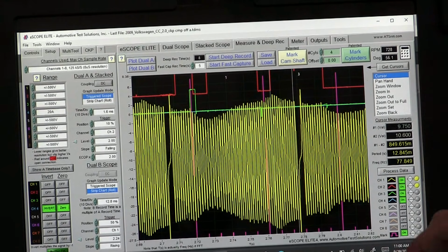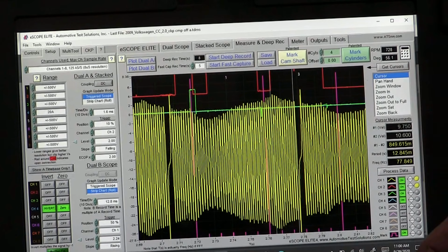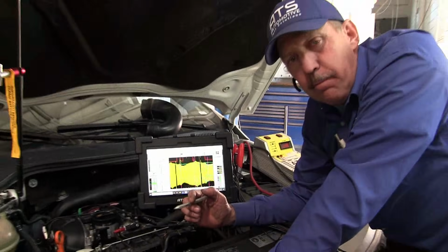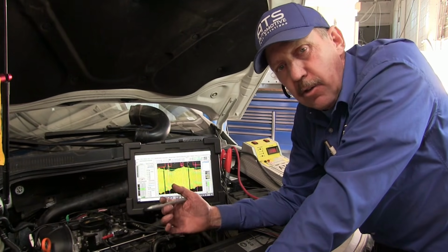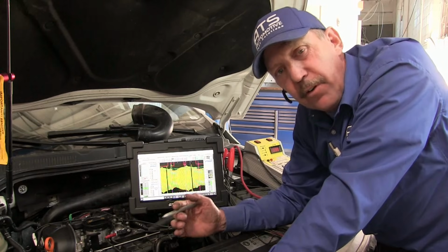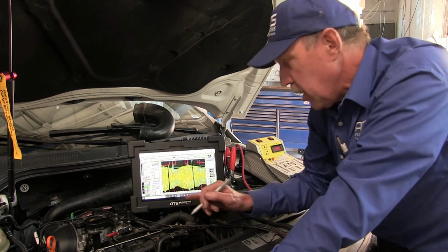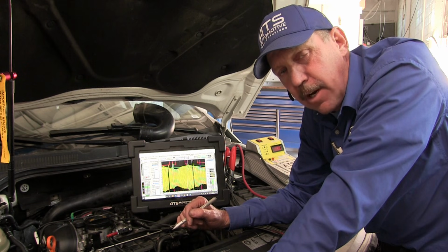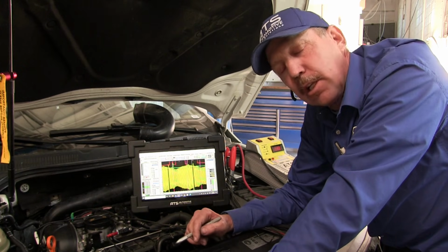That gives me, I'm about 56 degrees out of time right now. So this cam is quite a bit out of time. And we know that it's out of time because it lost the injector. It totally starts going all over. First it's moving its timing position, and then it's just gone. So that would also be an indication that the inputs, the cam and crank, are having a problem, and the algorithm can't figure out how to control it, so it's lost.